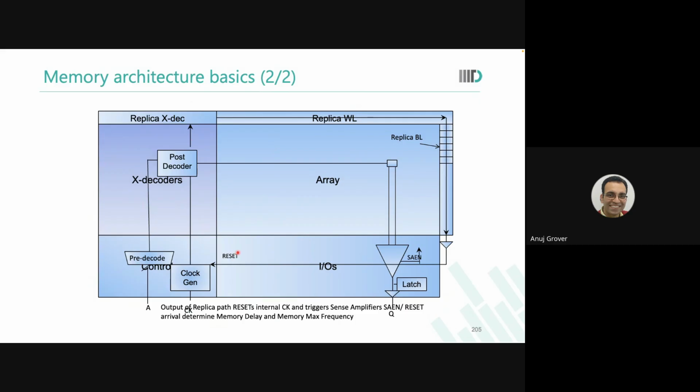So again, because you will read some other book somewhere and it will say that the farthest memory cell or the farthest sense amplifier is the worst memory cell. I'm already breaking that notion for you. It changes based on design. It changes based on the architecture. It changes based on the way you have done the tracking of your system. And you better be alert about it. Otherwise, whatever you design will start to fail.